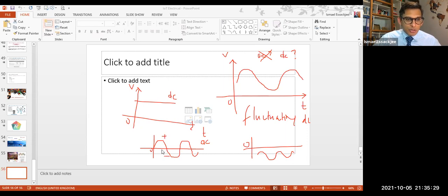Okay, next question. Why do we use drivers instead of transformers in low circuits and LED? With drivers, we have much more control. We can program drivers. Transformers take much more space, but with drivers, we can do much more. They're much more adaptable for our use and have much more flexibility.